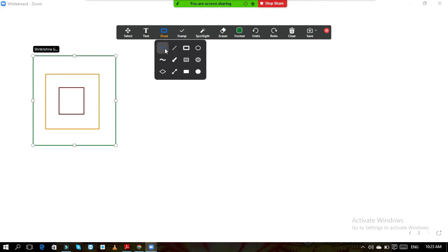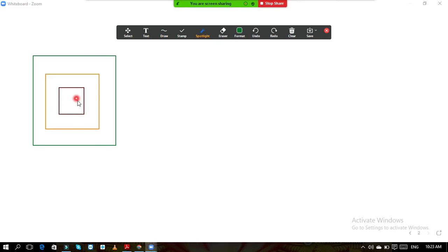So now see, if this column totally penetrates through the footing, then what will happen? The column will penetrate through this much area, whatever I have shown in yellow over here. So this much area will get deducted from this footing. Okay. So what area will remain? The remaining area will be this area.